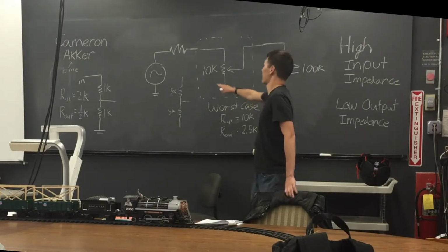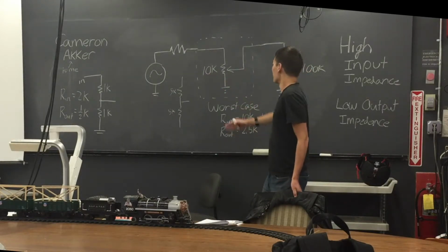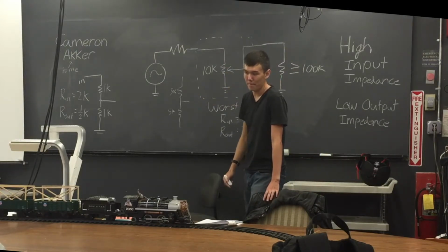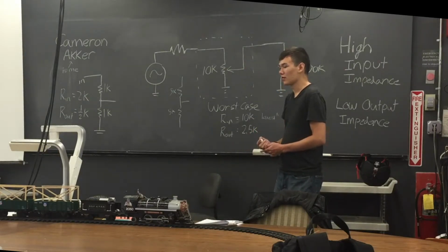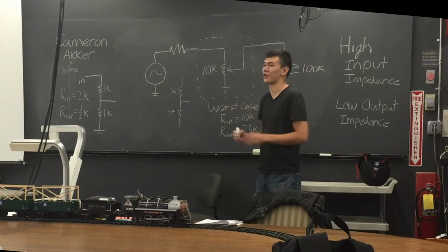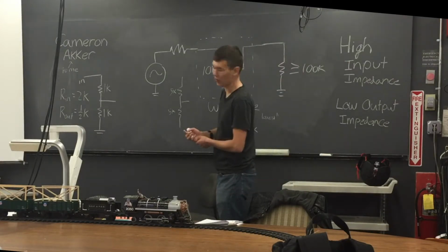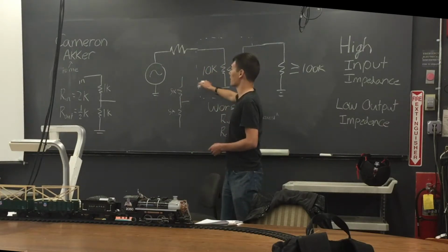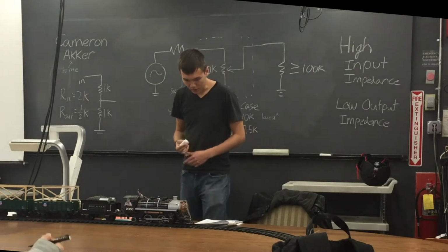I guess the weirdest part is the fact that the 10K output impedance is 2.5K, because if you think of it up here, it's 0, and if you think of it down here, it's 0. So if you pick the middle. Right. Okay, but so your output in that middle is not equal to the input in your next, because your next one is a completely separate box, right? Right. As long as you satisfy that condition, they don't affect each other. Okay. Did the problem ask you to pick a value for this one too? Yeah. Same with you, in this case it'd be 1K. If you pick 40, you could do 4K. Okay, I see. Thank you.